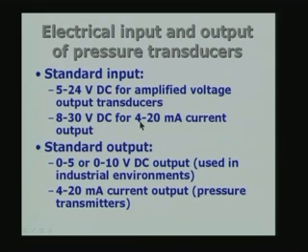If the current output of the instrument at the transducer is 4 milliampere, it corresponds to 0 or the minimum value of the pressure or whatever process parameter we are measuring. 20 milliamperes will correspond to the largest value which you can measure with that instrument. So, 20 milliampere is the maximum and 4 milliampere will be the minimum.